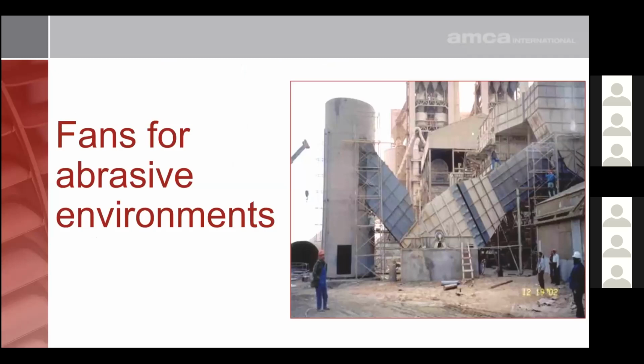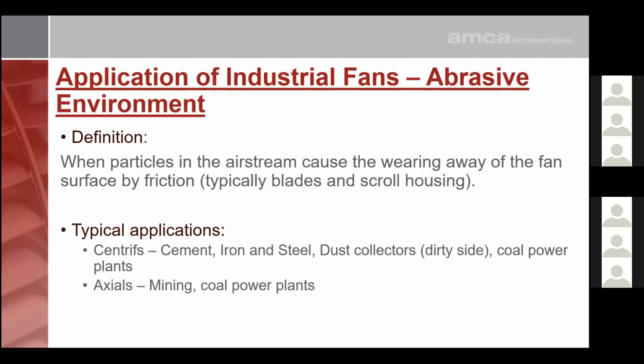First off, we have fans for abrasive environments. In the fan industry, we define an abrasive environment as one where the particles in the airstream cause the wearing away of the fan surface by friction. This typically happens at the blades and scroll of the housing. Some applications where we see high abrasion in centrifugal fans are in the cement industry, the iron and steel industry, with dust collectors, and in coal power plants. On axial fans, the main areas where we come across this kind of abrasion are mining and coal power plants.